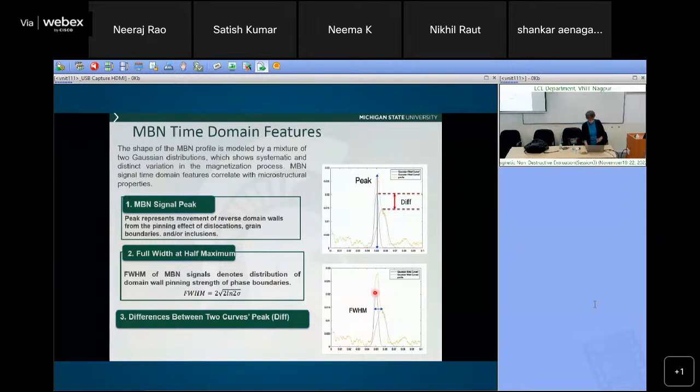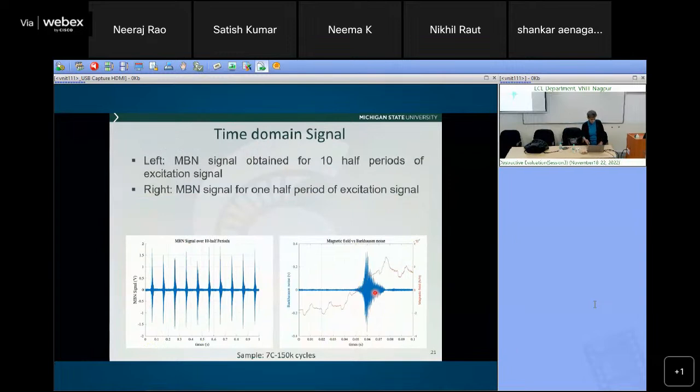When you take the spectrum of the received signal, you can see that the frequency is much higher than the excitation. So that 4 kilohertz or 20 kilohertz is for the pickup signal, because it's a totally different physical process. You've got magnetic field excitation, and the pickup is an acoustic signal. So it's totally different.